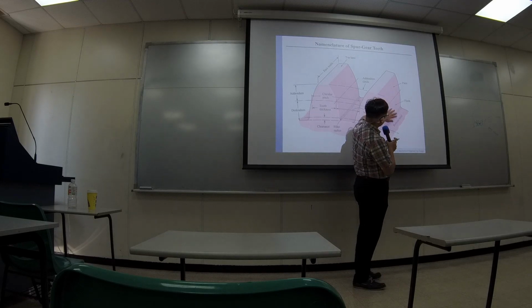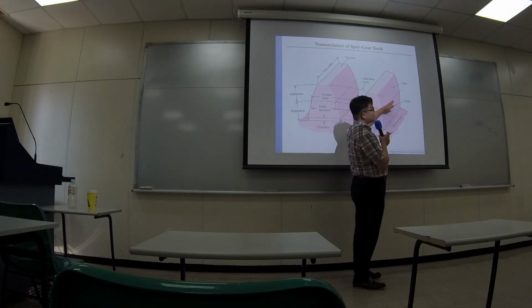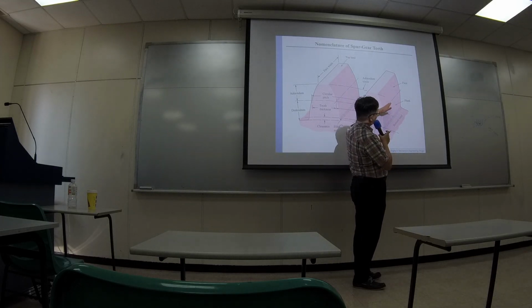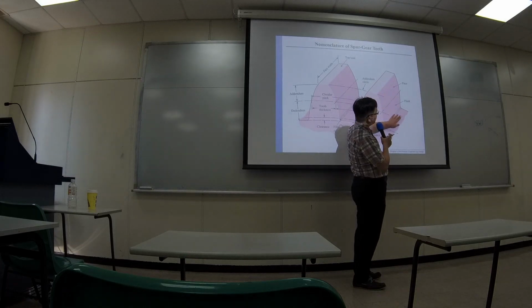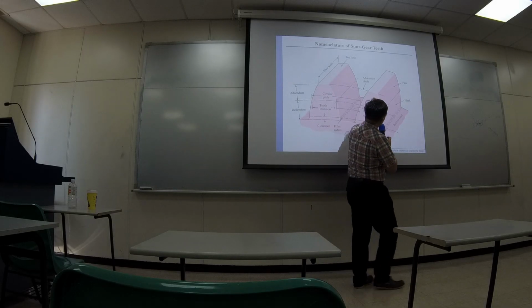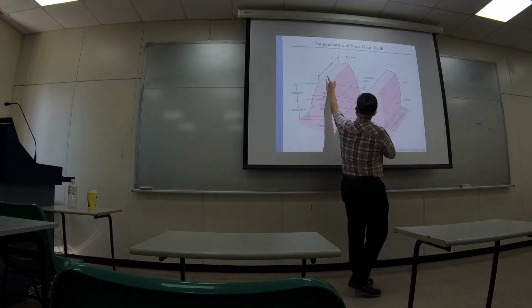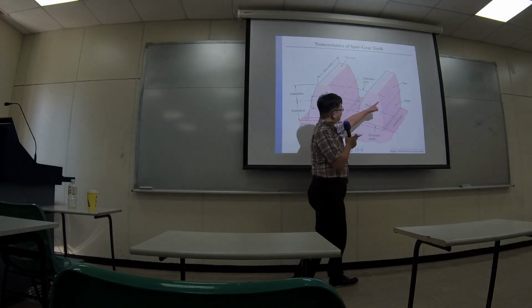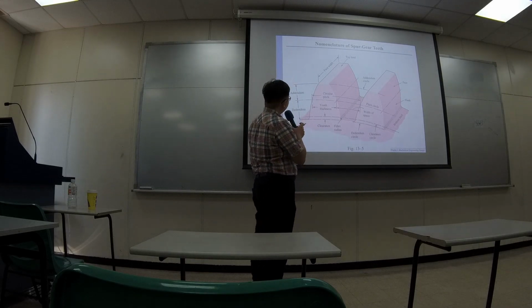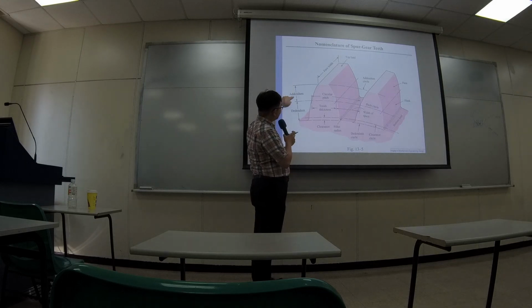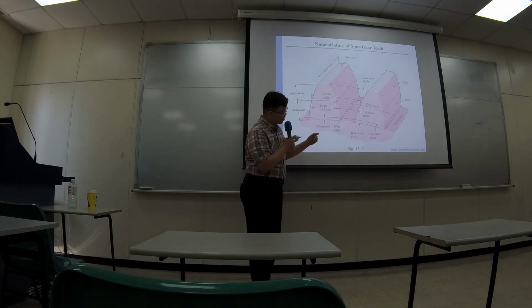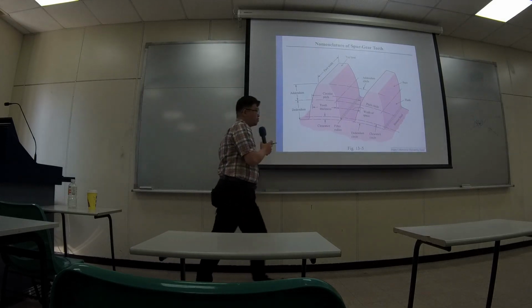Okay, on the side of the profile, separated by the position of the pitch circle, upper part is the face, the lower part is the flank. It's like the upper part of the teeth and the lower part. And the width of the teeth is called the face width, because this is the face, then this is the face width. Okay? And sometimes people call this upper part addendum and the lower part dedendum. Okay? They're just names. I think that's everything you need to know at this slide.